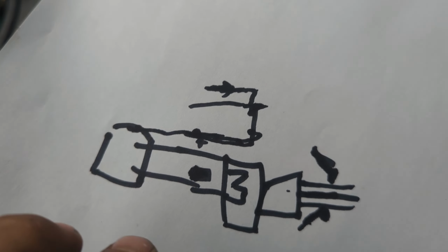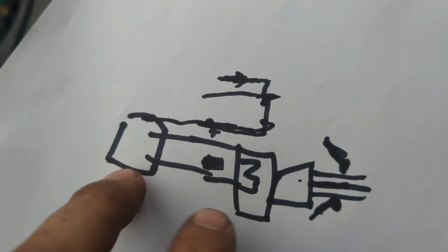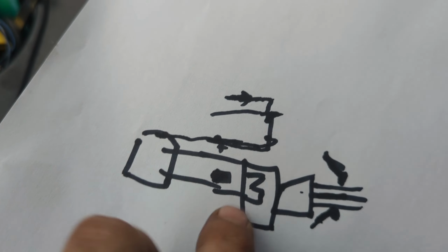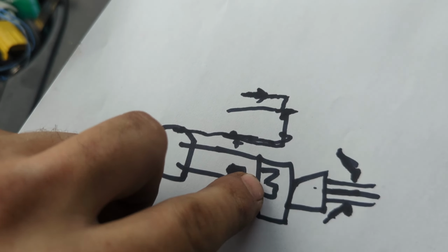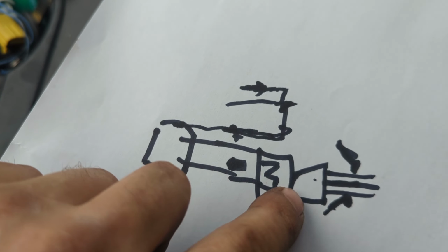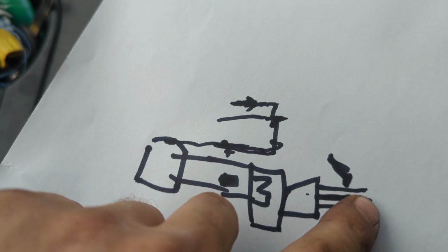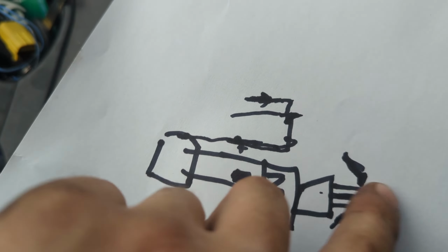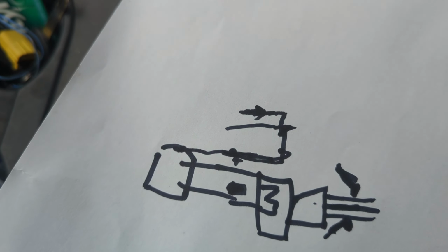Just remember, all that happens is that inside there's an igniter system. When there's a crash event, this igniter ignites. There's going to be a gas charge. That gas charge is going to push the cable backwards and lock it in spot in the back, but you will be able to move it back and forth a tiny bit.